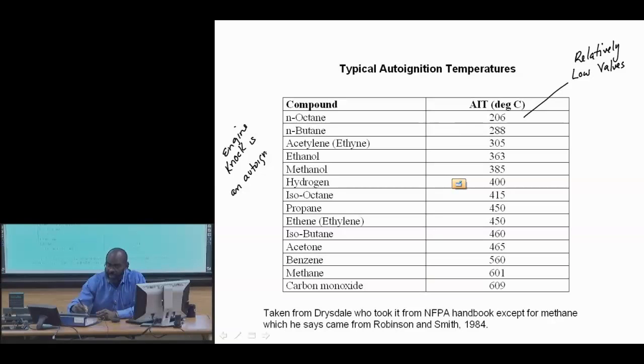It's this homogeneous ignition process that, again, occurs at relatively low temperatures. So that ASTM standard is very useful for understanding that aspect of the stability of the fuel-air mixture at temperatures that are, again, comparable to what you might see in cylinder issues, but less important from a fire safety perspective.